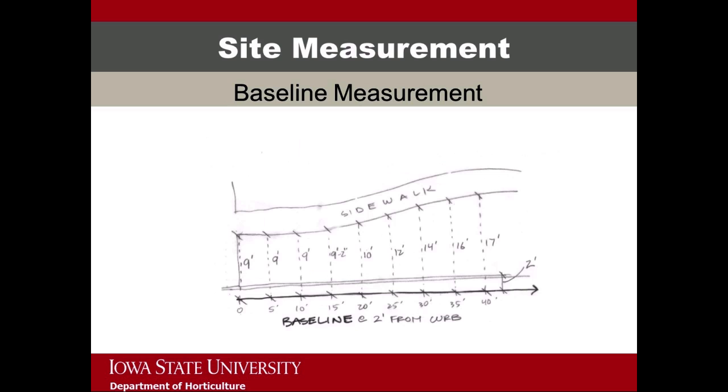Baseline measurement is a fantastic way to measure curves if the client has a curved planting bed or existing path. First, find a baseline. Maybe it's the curb or the edge of the driveway. Using that baseline, take measurements in set increments along the curve you need the dimensions for. The photo above shows measurements taken at 5-foot increments and is a great example of what your sketch may look like after measuring.